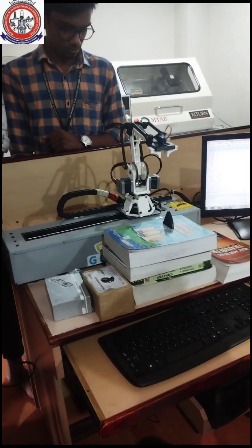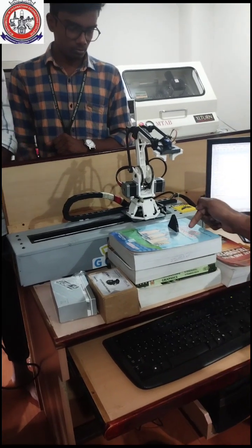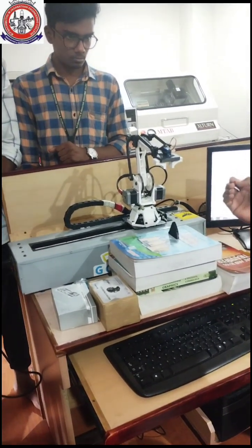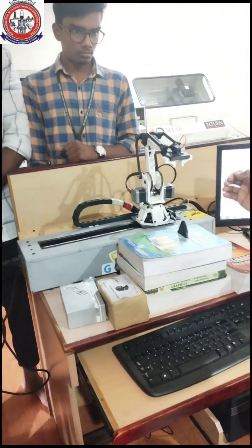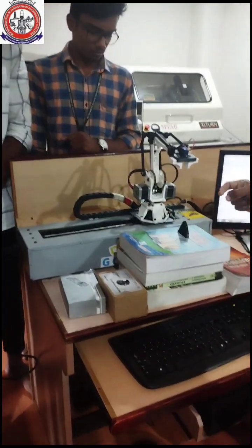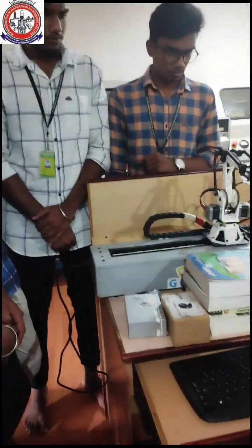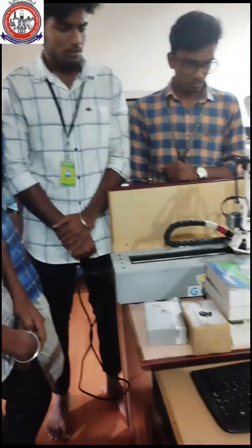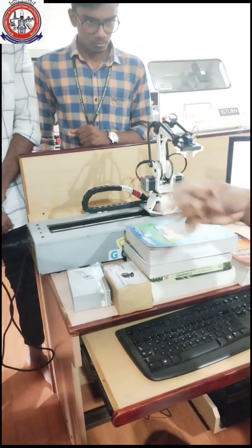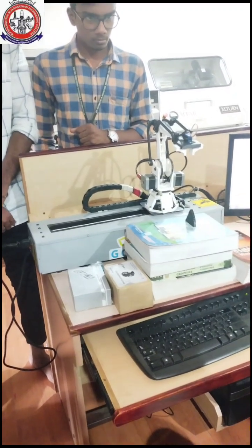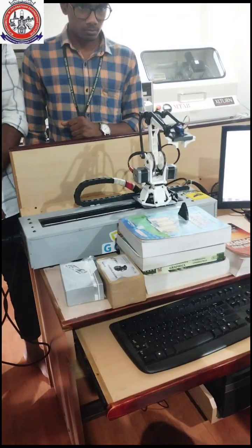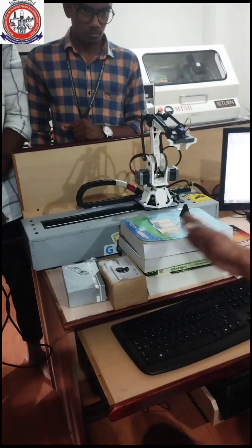Now we give a command to hold the workpiece. What axes are given? For example, if you give X20 or Y30, Y minus 30, likewise, it means the gripper, the robot, will come down to the workpiece and hold it. Then it will be given a command to move to another place. Wherever you place the object, it will be given a command based upon the coding, positive or negative. The value will be positive or negative based upon the distance of movement.